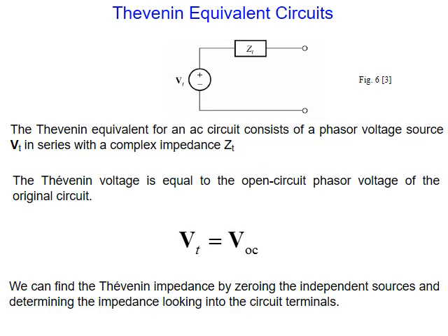Now if we go to Thevenin simply, when we deal with a complicated circuit that has many elements, and at specific points A, B, the terminals, we want to simplify, to reduce the circuit into just a supply in series with an impedance, similar to the discussion last semester in DC circuits, but it was with resistance. Here with impedance, as you can see, this is called the Thevenin equivalent circuit.